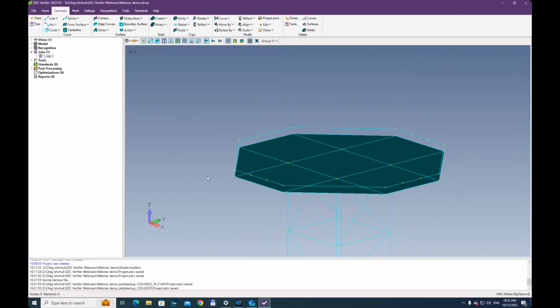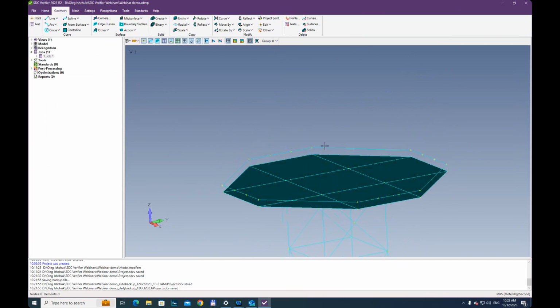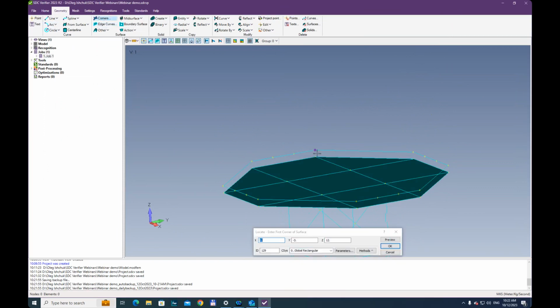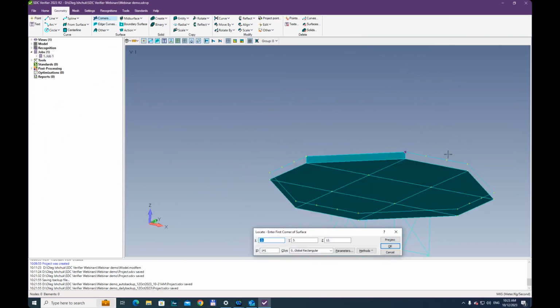Okay. And now I want to create the surfaces, these vertical surfaces here. If we want to keep the same logic, we can create them by defining the corners. So I click on corners and I say 1, 2, 3, 4, and I'm creating this kind of surface, right?